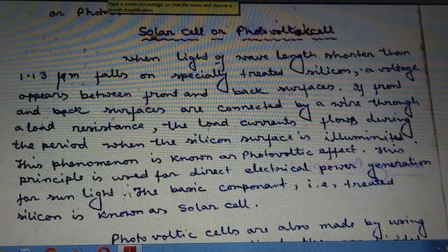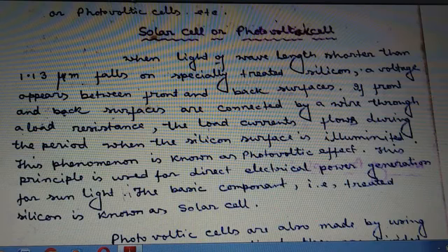These modules are again fabricated in series parallel combination in the form of a photovoltaic array, which is generally used in solar photovoltaic plants to have a huge amount of power to supply for residential or industrial applications. Generally, 36 solar cells are fabricated in series to make a solar photovoltaic module.